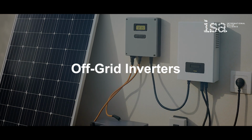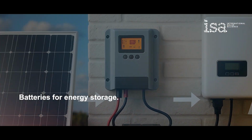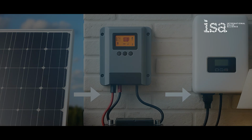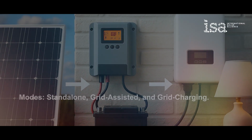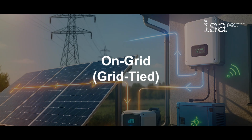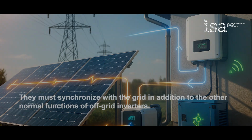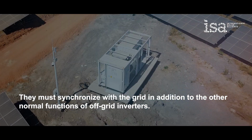Off-grid inverters, used in standalone systems without grid connection, depend on batteries for energy storage. They often integrate solar charge controllers, forming power conditioning units, PCUs, with modes such as standalone and grid-assisted grid charging. These are much smarter than the off-grid ones because they must synchronize with the grid in addition to the other normal functions of off-grid inverters.